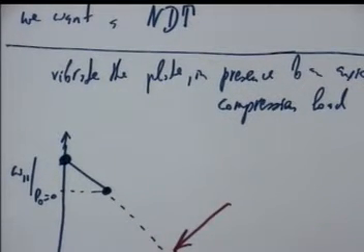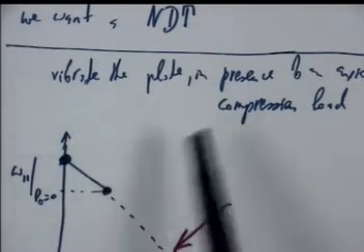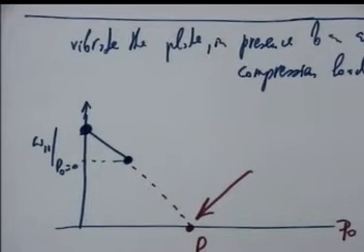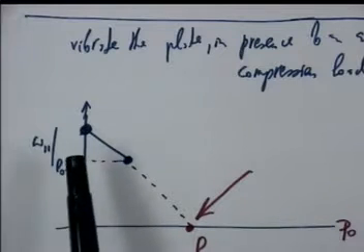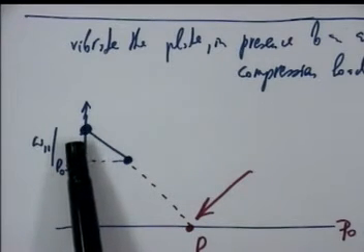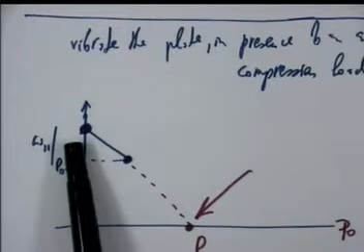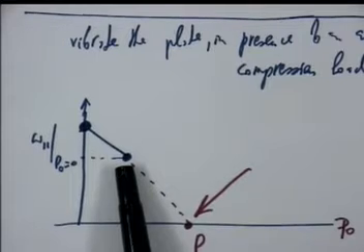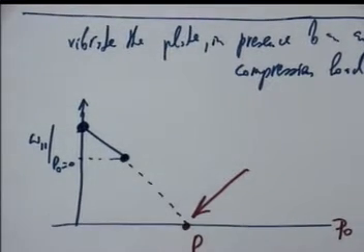Look, please. Vibrate the plate. If that is the case, we can, by vibrations, avoid buckling. What does that mean? We will vibrate the plate and measure the natural frequency. So, for example, first, do not put any axial load there. You will find the natural frequency, which you will put here on this figure. Now, just increase this load, but don't bring it to buckling. Increase this axial load slightly.